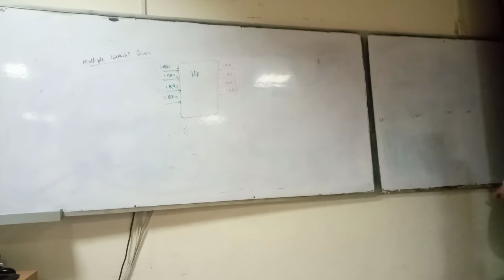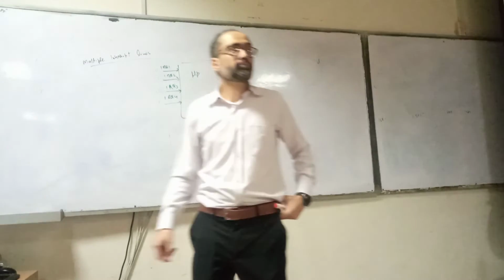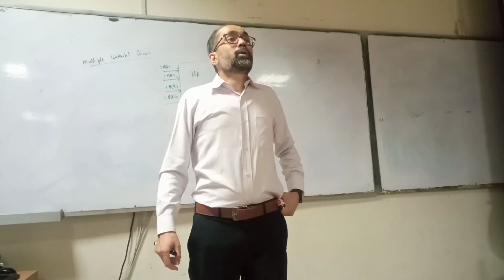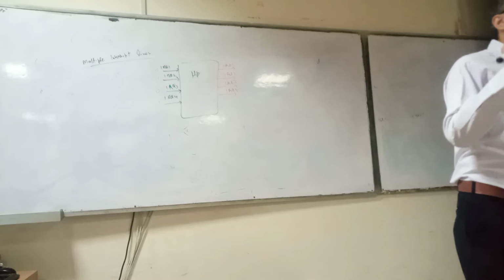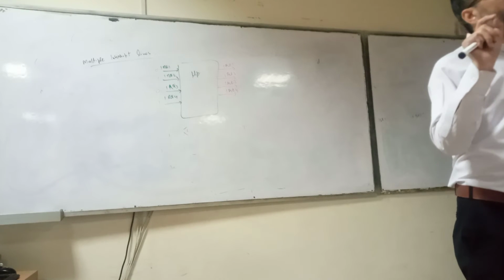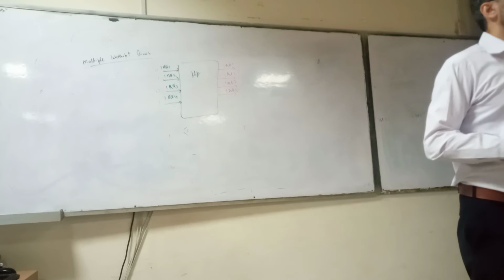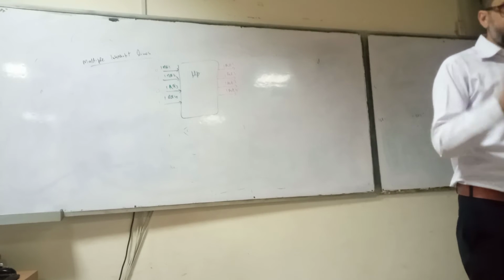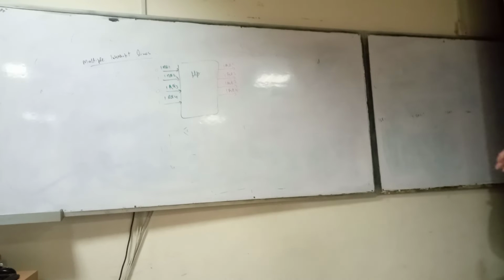Before jumping to the subroutine, what will the microprocessor do? It will push the program context. What are the different components of the program context? The working register, the status register, and the program counter. It will push them on the stack.